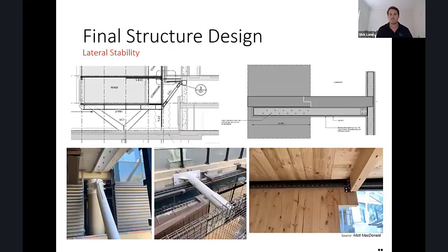with that is that you've got steel, which is a very high strength material over a small mass, whereas CLT is obviously highly stiff, but it requires slightly more material to be able to resist the same load. So we had to transfer a lot of load through the CLT, which required a lot of fixings, which was an interesting design challenge that we had with XLAM and Vistec, but we were able to achieve it in the end, which was great for the project. Next slide.